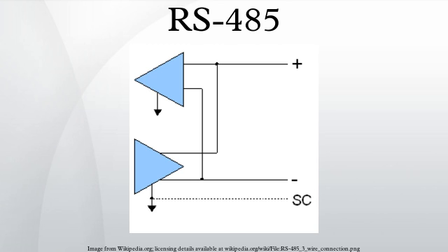Full duplex operation: RS-485, like RS-422, can be made full duplex by using 4 wires. Since RS-485 is a multi-point specification, however, this is not necessary in many cases. RS-485 and RS-422 can interoperate with certain restrictions. Converters between RS-485 and other formats are available to allow a personal computer to communicate with remote devices.